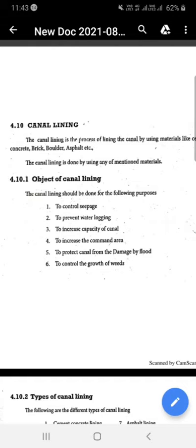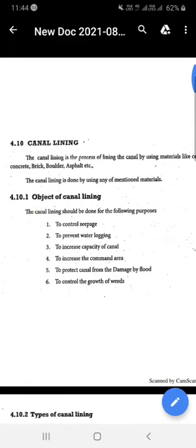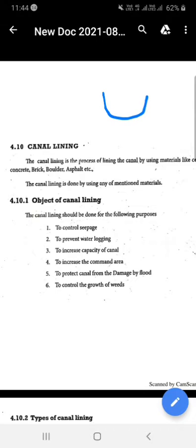But while flowing from one portion to another, there are certain losses that can happen, and the banks, meaning the surface, the wetted perimeter, can get eroded. So for that not to happen, due to the currents flowing along with the water, due to some losses due to eddy currents and such, we provide a lining. Suppose this is the channel, and we are going to provide a lining over here, so as to protect the channel from erosion. So that kind of losses we shouldn't have.